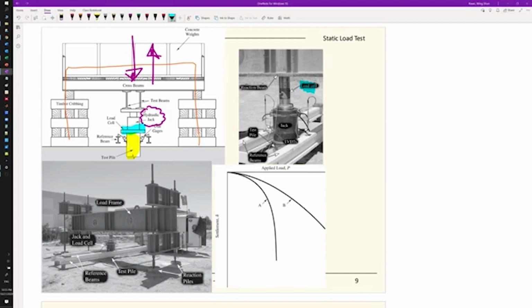Remember in the lab, you measure both the loading and the displacements, such that you can get the stress strain curve for the response of the soil. Here it is a little bit more complicated. You get the load displacement response of the pile and soil interactions. When you load the pile, it's not just the pile, because you also mobilize the soil around it, both at the toe and at the side friction. We talked about the mobilization a couple of slides before.